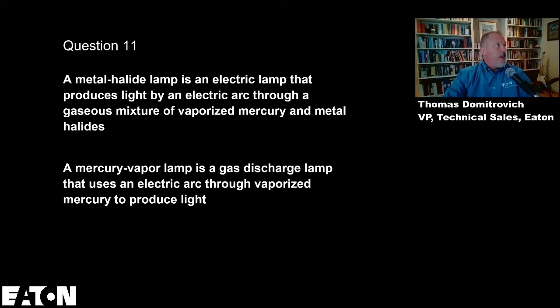I know that we have special lighting for the sports arena events, not just from a protection perspective, but for other reasons as well. And now this specifically talks to metal halide and mercury vapor. Now, if I'm using LED lighting, I wouldn't have that same requirement because you don't have that same vulnerability. You don't have the gas discharge lamps and electric lamps and things of that nature.